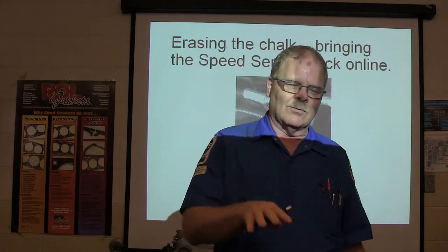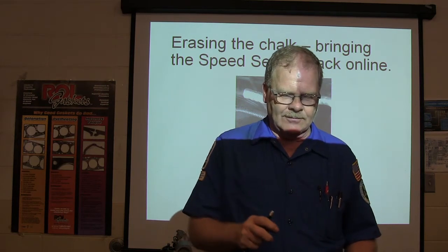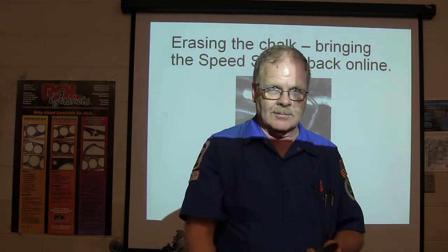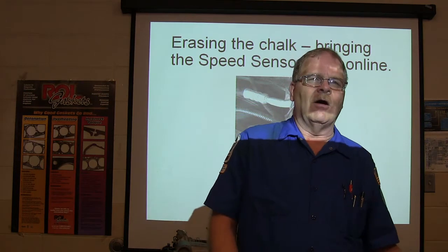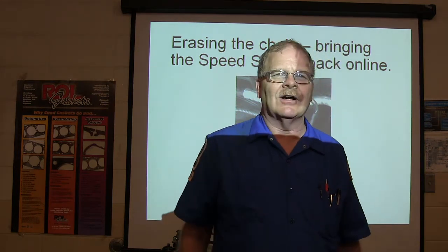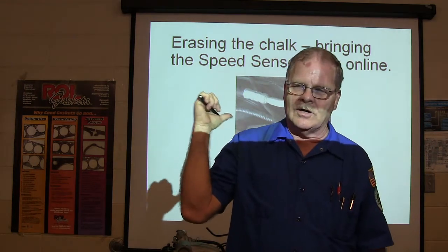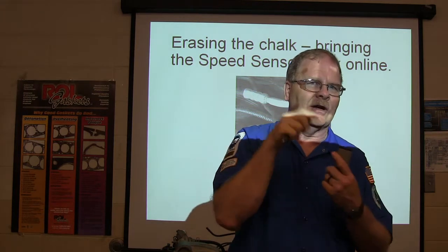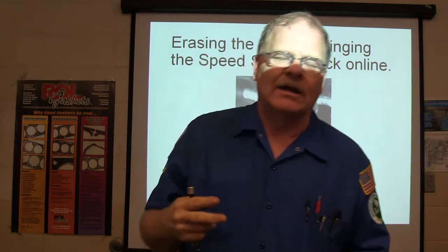So what I did was, I checked the fuel pump, going back to the fuel pump, if you've got a ground coming through the motor. Nope, I don't have a ground coming through the motor, so off comes the tank, I pop a fuel pump in it, and I still got no start, still got no ground through the motor. And this same sort of thing was going on with that Taurus. It had chalky stuff you couldn't see without unplugging the connector, and that's where the ground was, all the way back to the battery. You know what I mean? So I went ahead and fixed that.